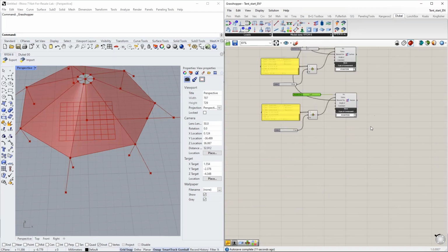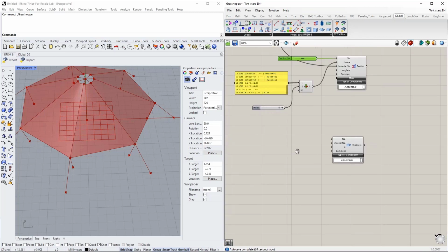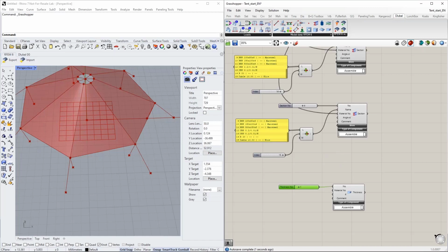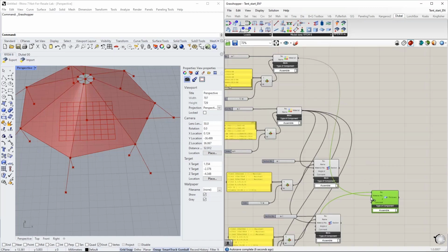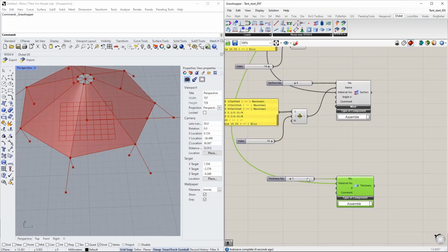The next step is the definition of a thickness, the thickness I need for my membranes. Yeah, a surface needs to have a thickness assigned to it. This is the new RFEM 6 logic, and therefore I'm creating a thickness here with this component. Quite easy to use. Copy paste the index number, using it again, and then the material number. This is then material number 1, the PTFE material, and there's one speciality.